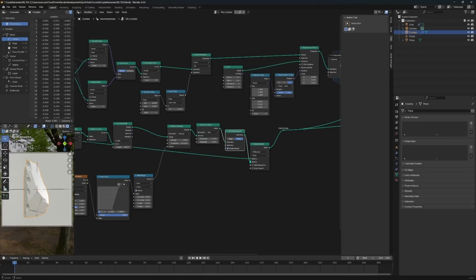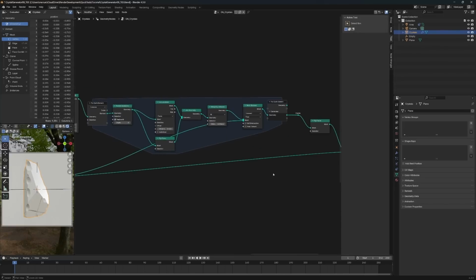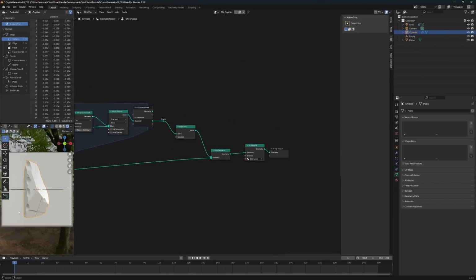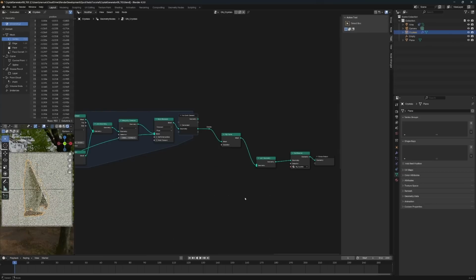This will smooth shade only these indents. And as you can see, we have these lines here from the inside cracks. What I want to do now is create an edge value for these inside planes that I can use as a mask to mask them off in shading. So for now, let's just cut this connection to just see the inside.